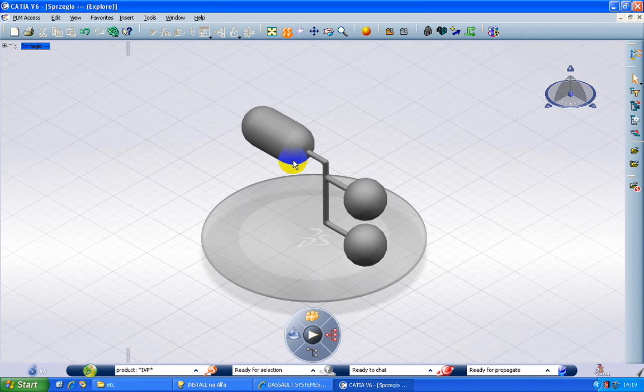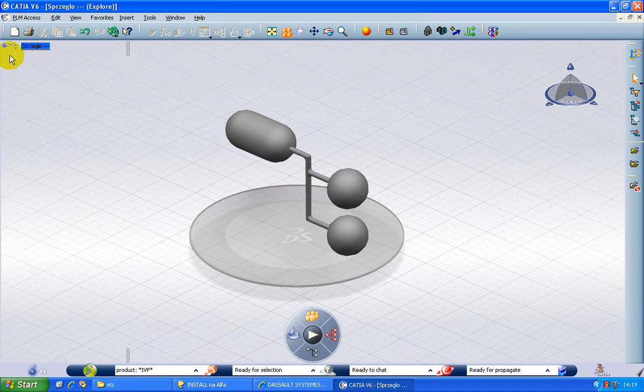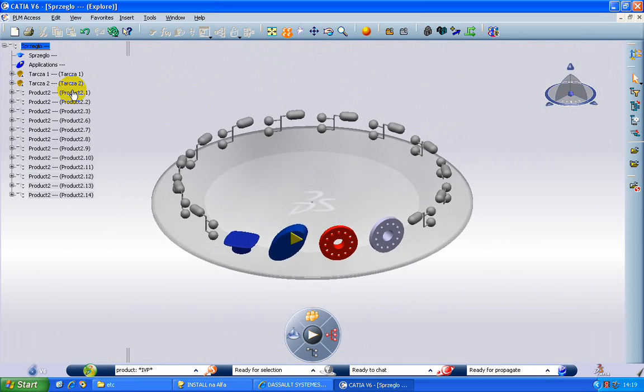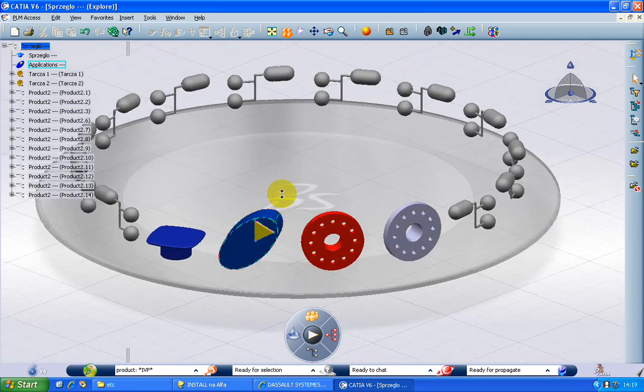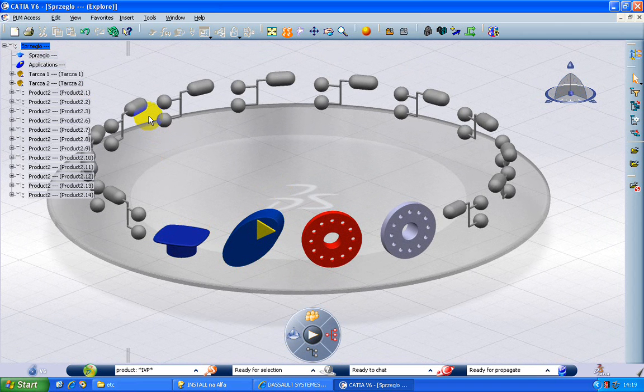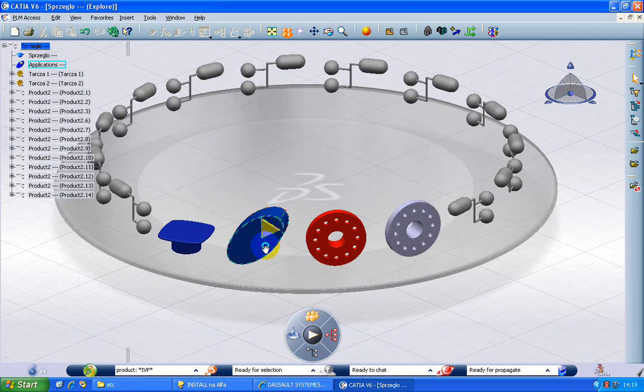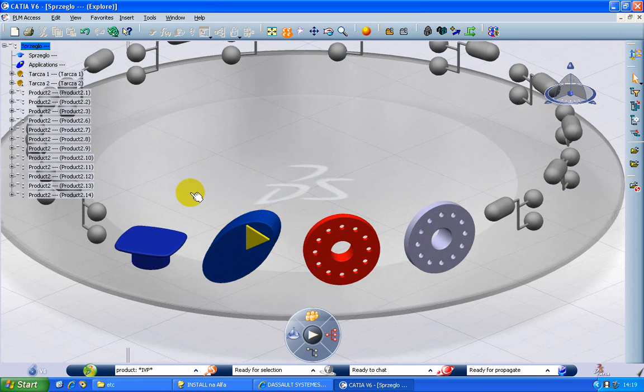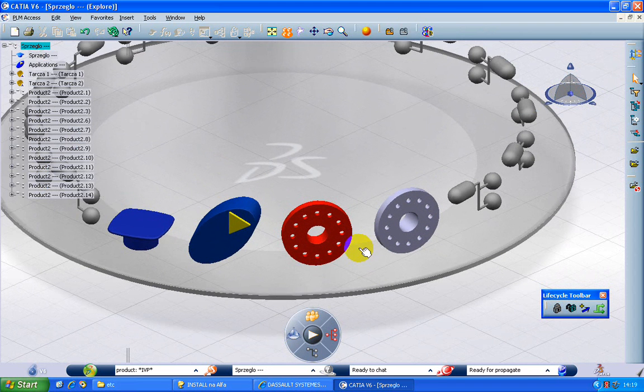And that's it. So what we have seen now is import, advanced search, and explore. Explore is just the sub turntable, okay? I don't remember if I told you or showed you. You remember if I wanted to explore it, I have to double click on the turntable or on the symbol to see if there's something inside. If I don't want to explore it, I use this sub turntable. If I don't have this sub turntable icon activated, I won't be able to explore it on the turntable. I have to activate it, and then double click. Okay?